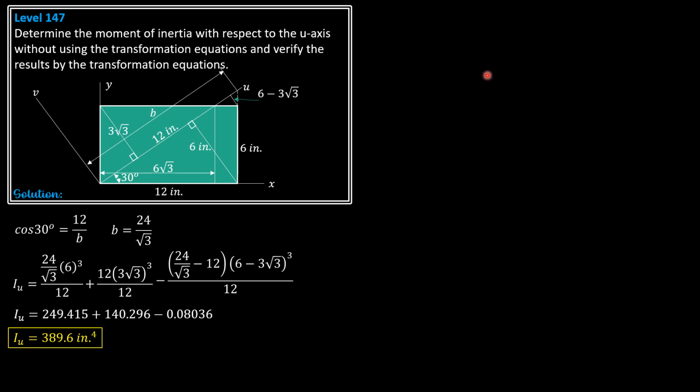Then minus Pxy, the product of inertia x sub y, times sine of 2 theta. So that's the formula for I sub u. That's the transformation equation for moment of inertia.